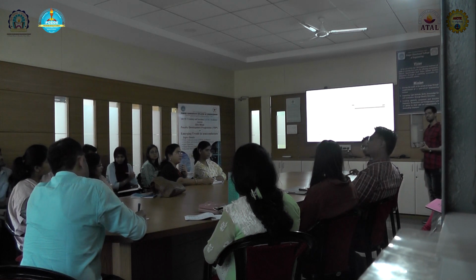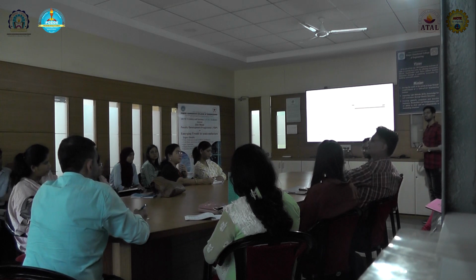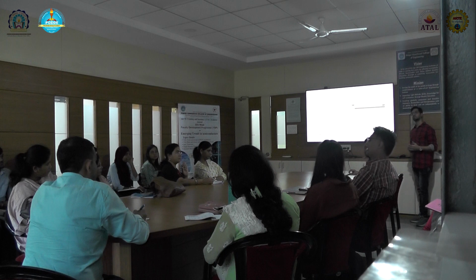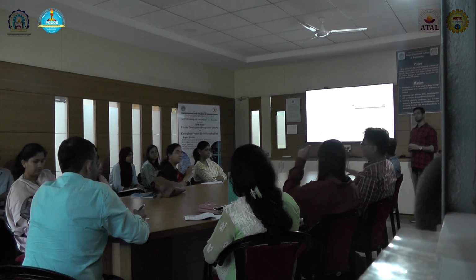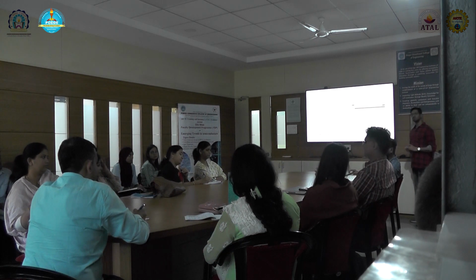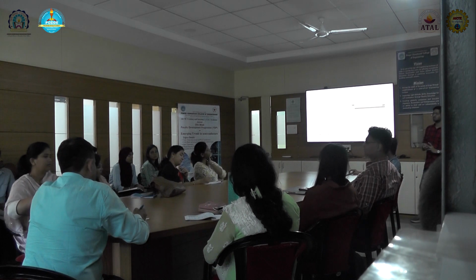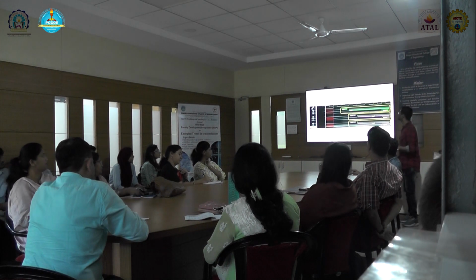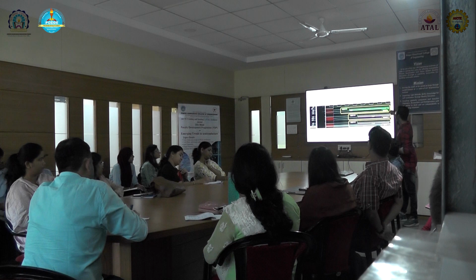So it is not trying to fail this property. It is trying to find a waveform, and it will show where it is generated, and mark it as done. It will show you that okay, I have tested this scenario and here is the proof. This is the waveform. I have tested this scenario. So it will find a scenario where done 1, done 2, and done are getting high in the same cycle.